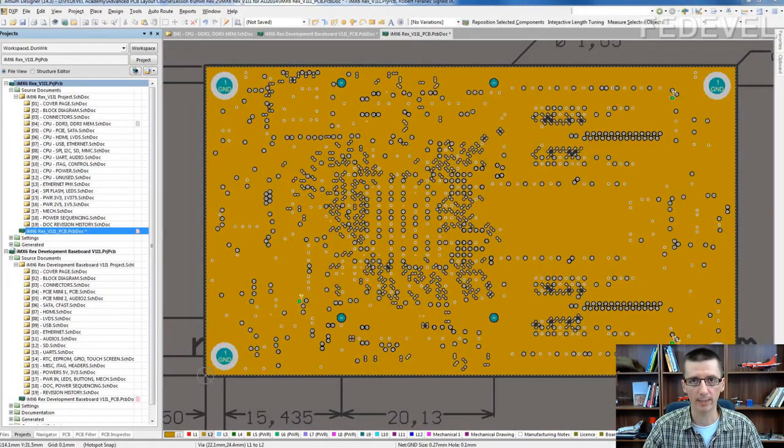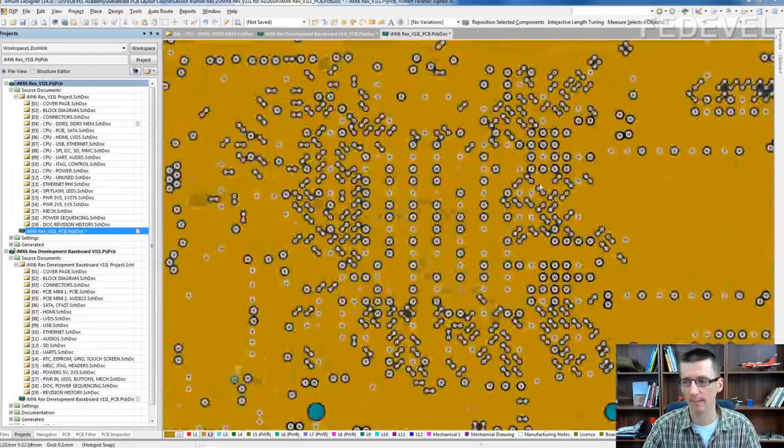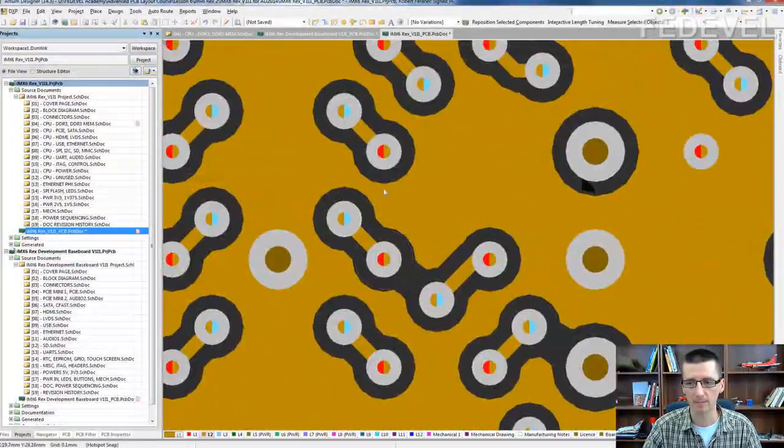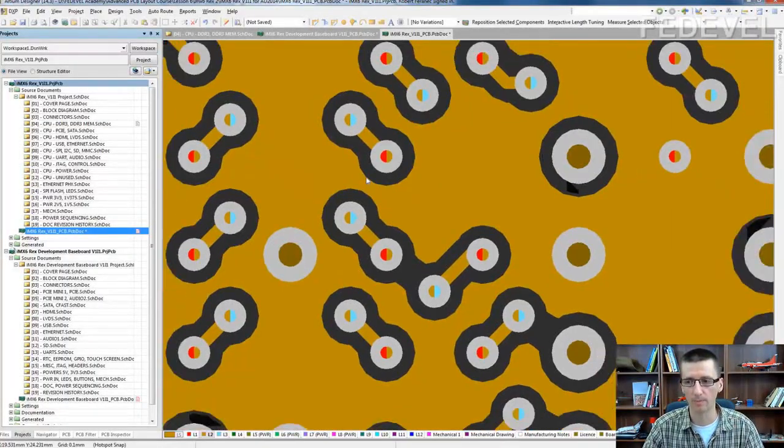Very similar way, we can improve also the polygons on layer 2 and layer 11. These are the layers with the short connections between microvias. And you can see in busy areas, this copper is very small. What can we do? Instead of using default 0.1 millimeter, we can use something smaller.